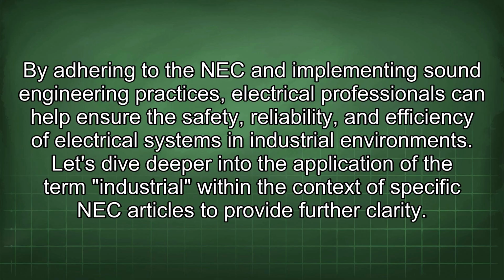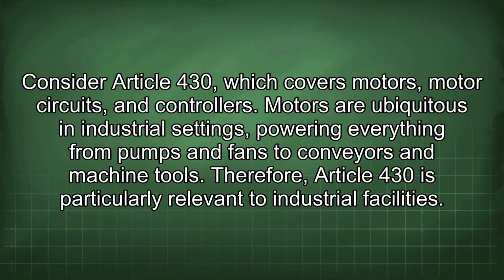Let's dive deeper into the application of the term industrial within the context of specific NEC articles to provide further clarity. Consider Article 430, which covers motors, motor circuits, and controllers. Motors are ubiquitous in industrial settings, powering everything from pumps and fans to conveyors and machine tools. Therefore, Article 430 is particularly relevant to industrial facilities.